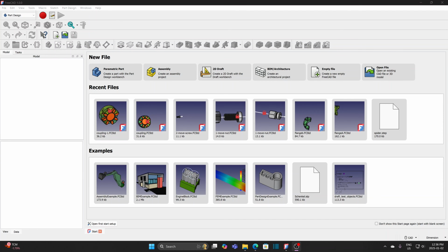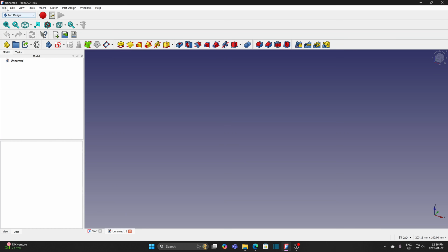In A2+ Workbench, there is a point-to-point constraint, but apparently, it is not in the new Assembly Workbench. Sometimes, I do need this when other constraints are not applicable or not convenient to use. Let me do a point-to-point constraint by this example, flexible coupling. Create a new file.